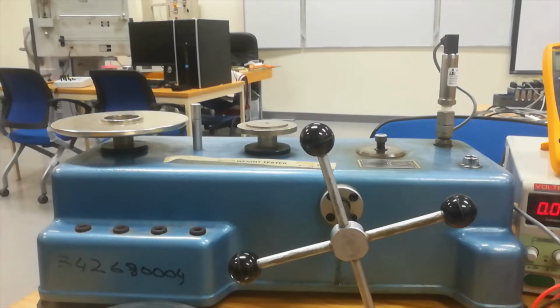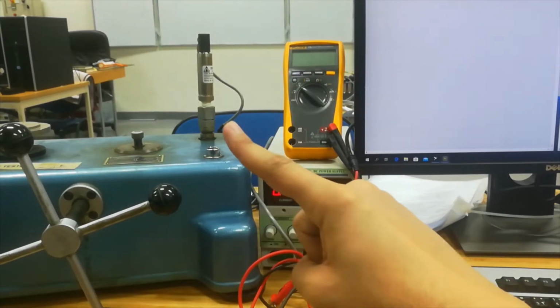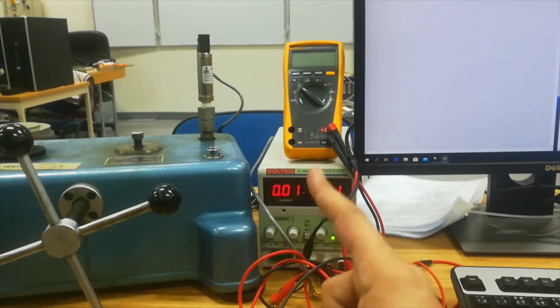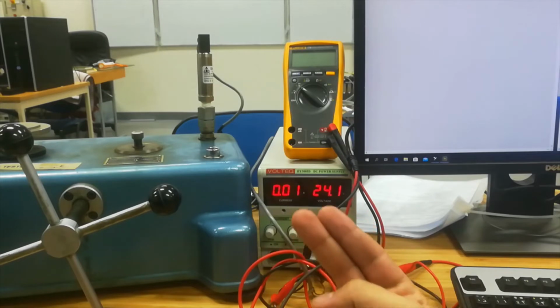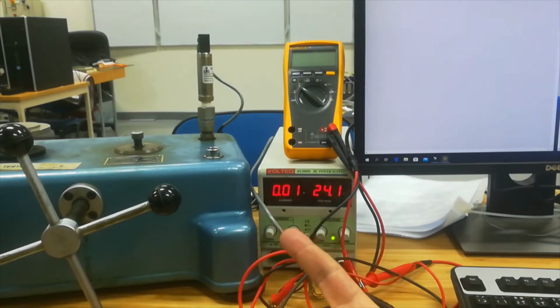So you are converting the pressure to a change in the resistance, but you cannot measure this resistance using a data acquisition card. Then you need to excite it. That's why you will find that we have a power supply. So the output from the pressure transducer is resistance, and we have a power supply. Once you adjust the voltage of the power supply, you are expecting to get a current corresponding to this voltage. Multiplying the current coming out from the power supply with the resistance, you will get the voltage corresponding to the resistance, corresponding to the measured pressure.